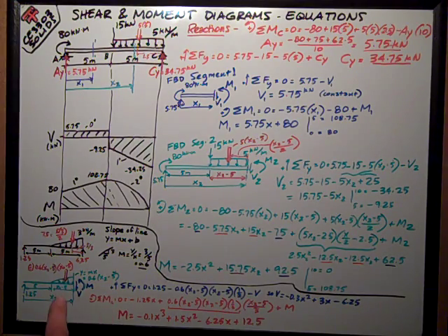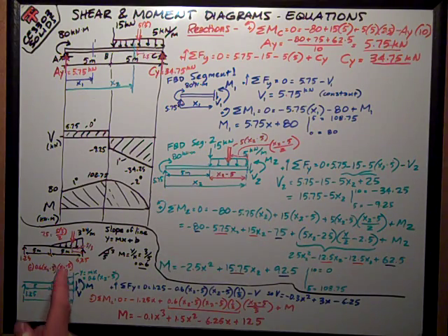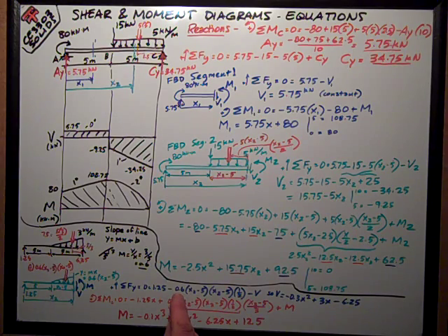Okay, so let's say we're going to write a segment, one of these like segment 2, out here in the middle of the span, in the right half of the span, to the right side of the half point. It gets complicated real fast. My sum of forces in y equals 0, which is my reaction minus this force, which is the slope, 0.6, times the x distance.